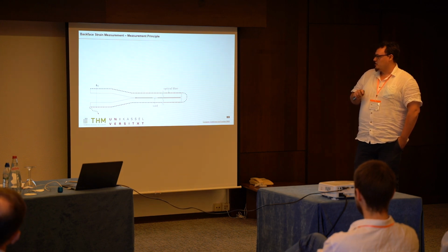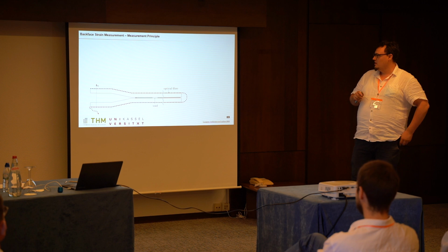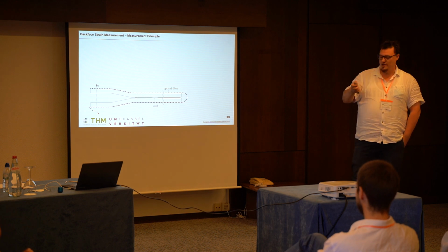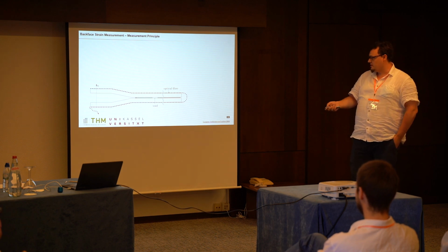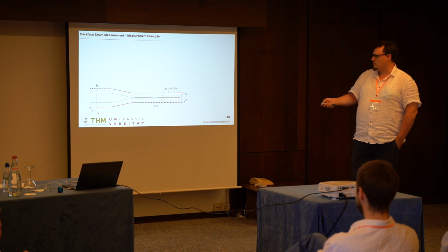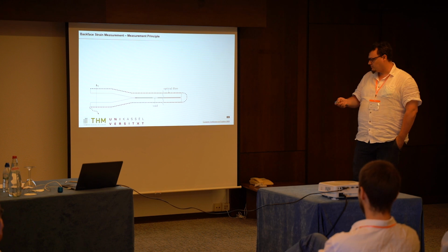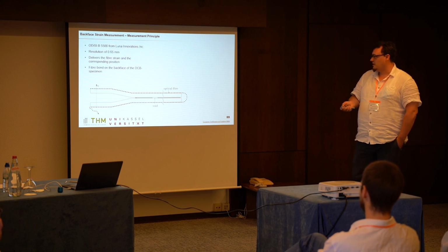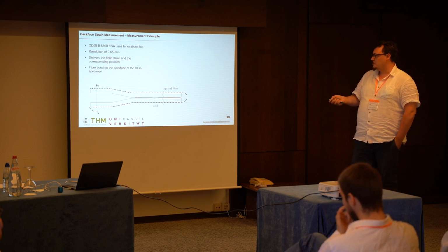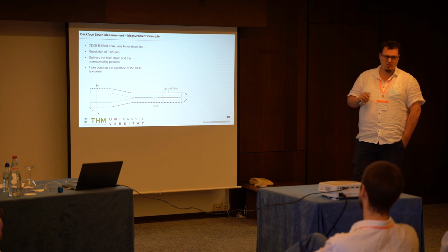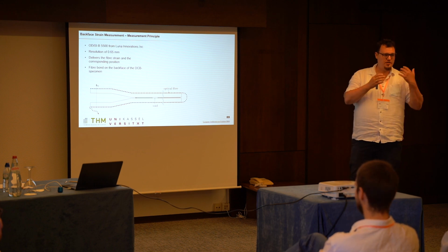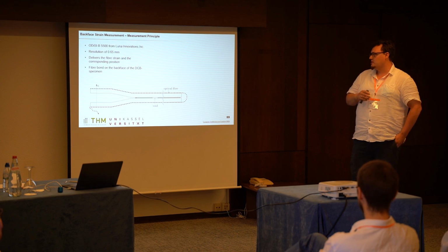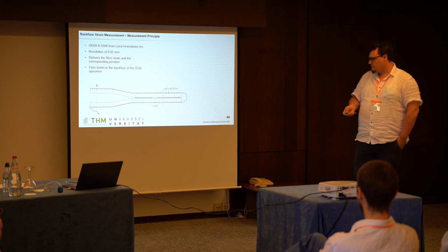Now, backface strain measurement, the name says it. We measure the strain on the back face of the adherend. Therefore, we use the optical fiber. We bond it here like the red dotted line. As device, we had something from Luna Innovations, and with the system, we are able to measure the strain every 0.65 millimeters in the fiber.